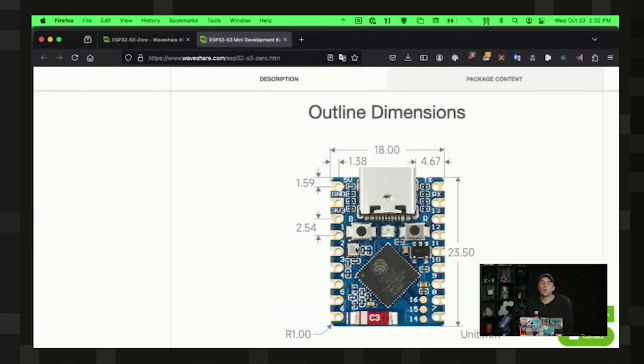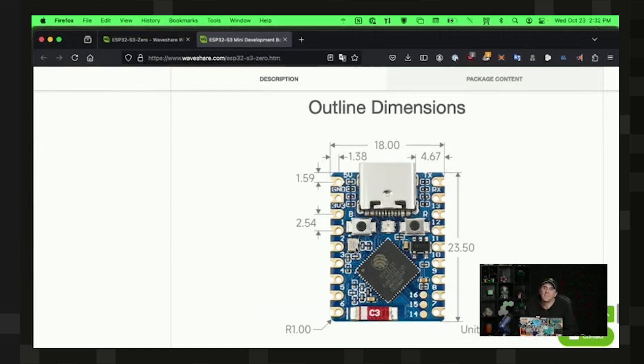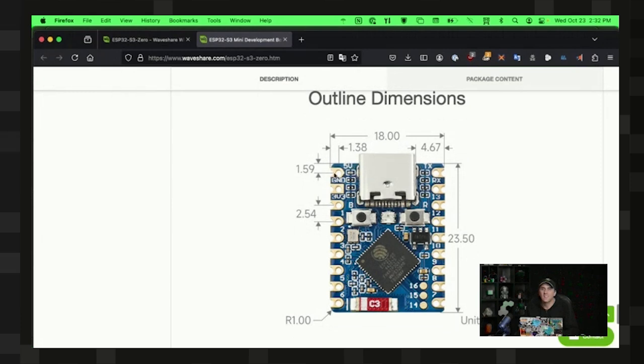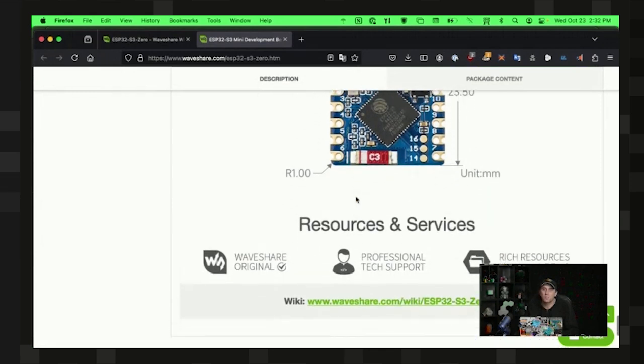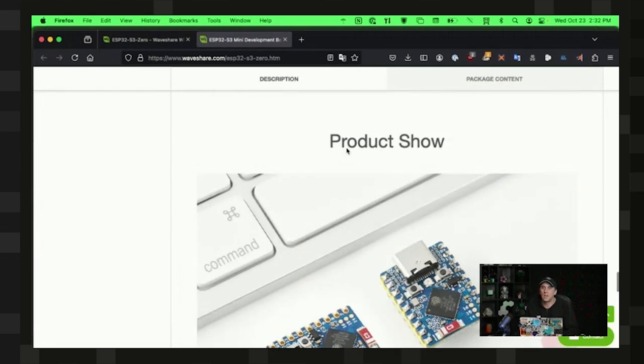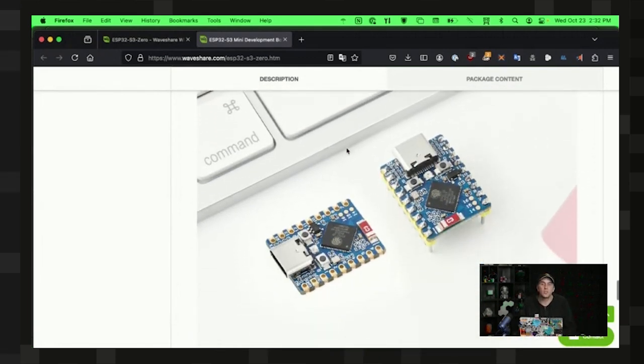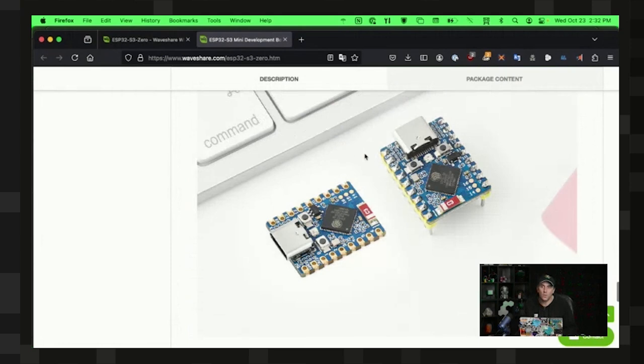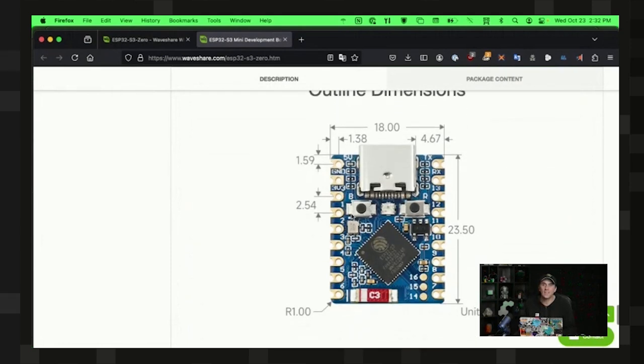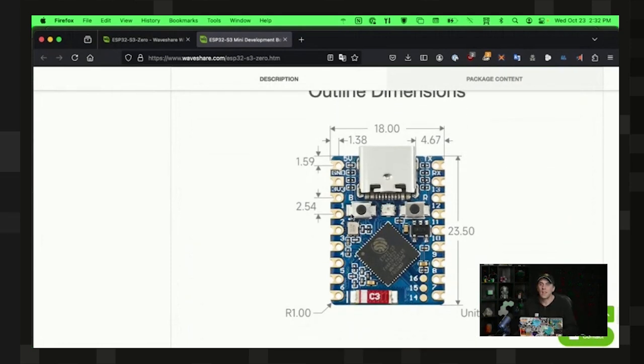If we want to make our own footprint, this is more or less exactly what we need. So we might need to get the actual pad size a little bit correct, but for just making a rough footprint, associating it with the correct pins, it shouldn't actually be that difficult. So let me show exactly how to do this in case you want to use something like this and create an SAO or something like that using a footprint.